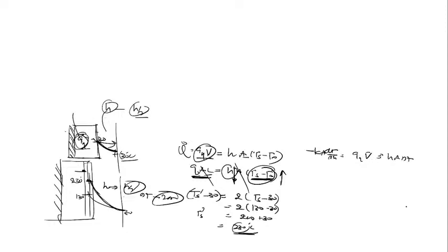Clear? So what I'm saying is that whatever is going to be generated is going to be transferred by conduction in the material. So at x equal to L, here in this case, is also equal to h delta T. So what about the gradient? As I told you, Qg into volume remains the same, then dT upon dx will also remain the same. That will not be changed. Yes or no?